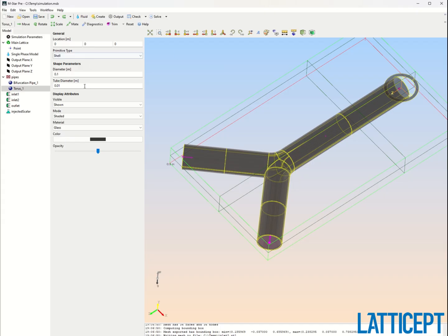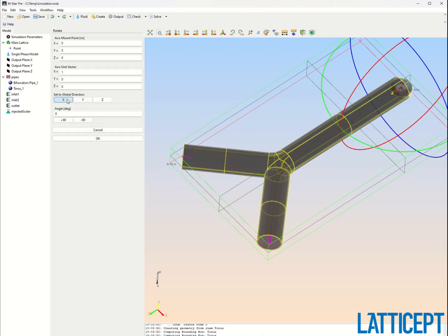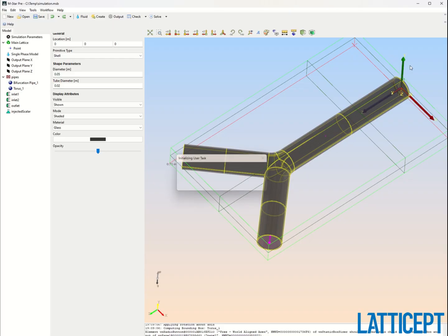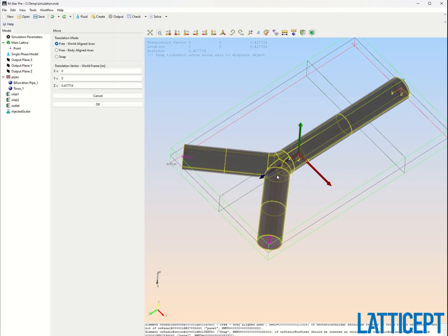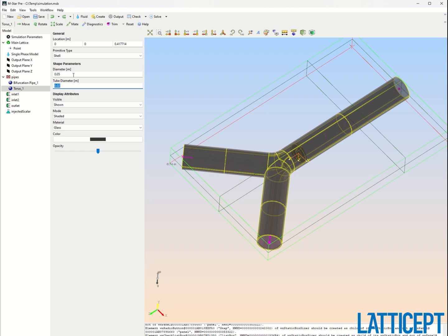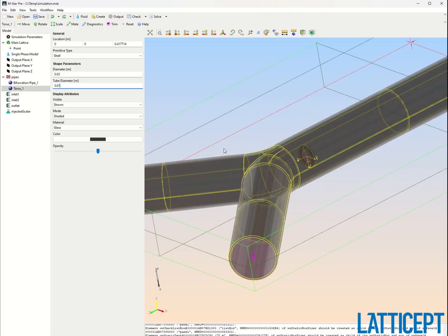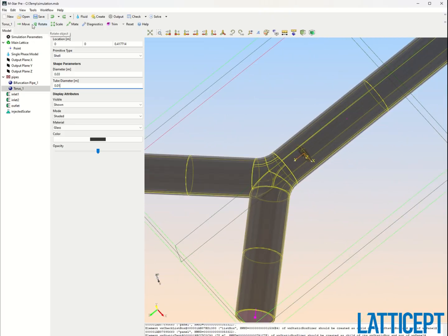It comes in down there. I'm going to change its shape to 0.05. And again, I'm making this up on the spot here, so cut me a little slack. And we're going to rotate this by 90 degrees. Okay, and then we're going to move it where we want it. We want to move it up here to the inlet. I still think it's too big, so I'm going to adjust the shape here, 0.03. And again, I'm just eyeballing this, 0.01, because all we're trying to do is create some turbulence,